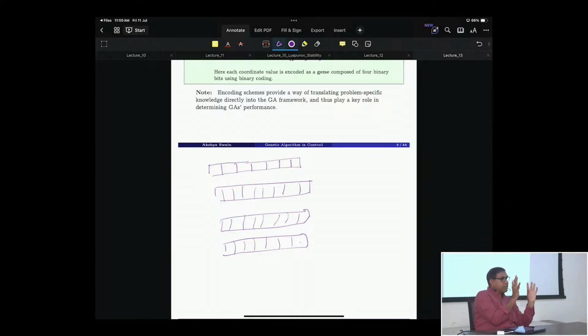Say, for example, that 8-bit can be between 0 to 255, or minus 127 to 128, or minus 20,000 to plus 20,000. It is all the scaling factors. You decide the range of the number. While designing the controller, you say my KP value should be between, say, 1 to 5, but you are representing that by an 8-bit chromosome. So I'm just explaining these things here.